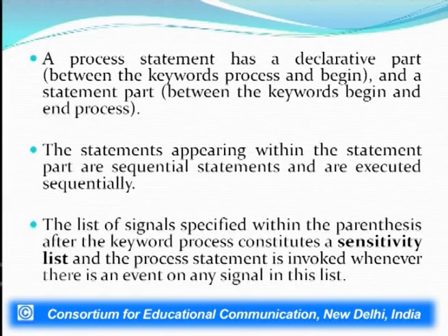Now it is very important here to get into a little depth of what this process statement is capable of doing and what is the physical significance of having this statement. Now the process statement has two parts, a declarative part which is placed between the keywords process and begin, and a statement part which is between the keywords begin and end process. Statements appearing within the statement part are sequential statements, executed sequentially like I just mentioned, and the list of signals specified within the parenthesis after the keyword process constitutes the sensitivity list. The process statement is invoked whenever there is an event on any of the signals in this particular sensitivity list.